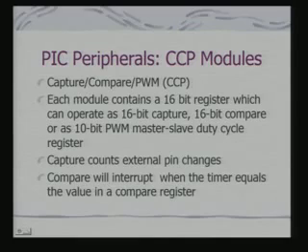Each of these modules contains a 16-bit register which can operate as what we call a 16-bit capture register, a 16-bit compare register, or as a 10-bit PWM master slave duty cycle register. Capture counts external pin changes, and compare will interrupt when the timer equals the value of a compare register.